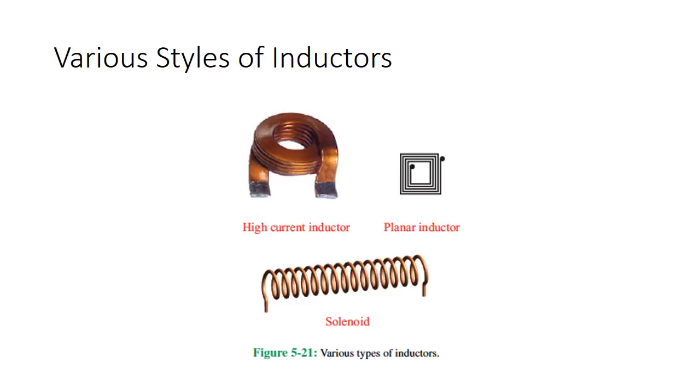So if you go back to the electrical engineering lab in HH126, you'll see on that shelf that there is an inductor there and a solenoid inductor. It has a pin inside of it, and if you flip the switch on while the pin is in, it'll suck the pin into it. And if you flip the switch off, then the pin can come out. But if the switch is on, you're not going to be able to pull that pin out. And likewise, you can do solenoids in reverse to make coil guns or rail guns, to be able to launch a projectile very quickly using a magnetic field.